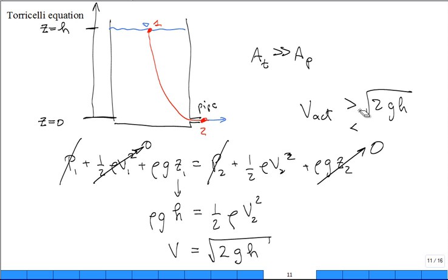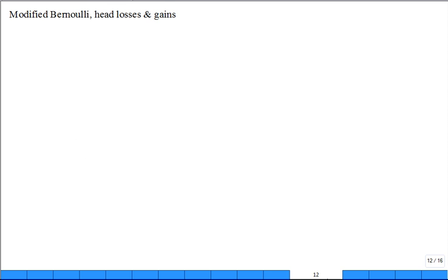Because of friction. It's really hard to shove that water into the inlet of the pipe. And what we'll learn later is that if you make the inlet to the pipe square, it's not as good. If you make the inlet to the pipe where the pipe protrudes into the tank, that's even worse. The best would be to blend it, make a smooth transition in there so that you don't get flow separation. You don't want to have separation. That's viscous. I have to stop right now. We'll pick up here next time.